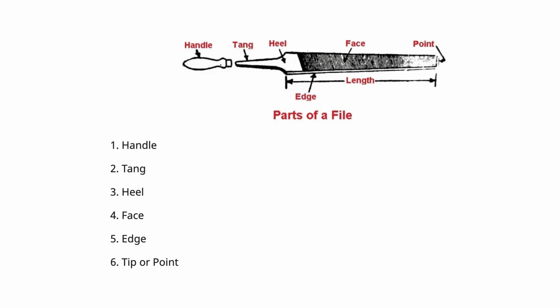Initially we have a big metal sheet, 4 by 8, and from it we take a piece which is relevant for us to make a splint. When we cut the piece with the help of a hand shear or a metal cutter like scissors, extra debris and very sharp cutting edges are produced. So to remove all that extra debris and to make it smooth, we use files.